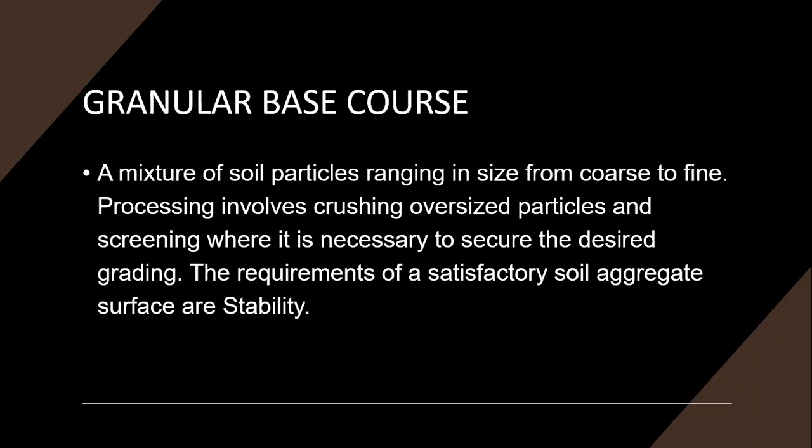Next is the granular base course. Now, granular base course is a mixture of soil particles ranging in size from the coarse to fine. Processing involves crushing oversized particles and screening where it is necessary to secure the desired grading. The requirements of a satisfactory soil aggregate surface are stability.